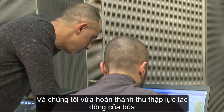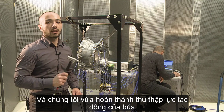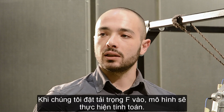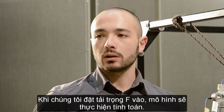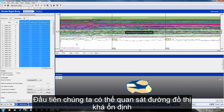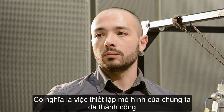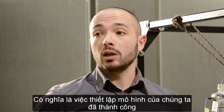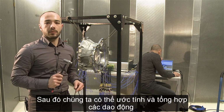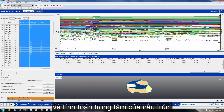So now we just finished acquiring all the FRF with the impact hammer. When we load those FRF in the rigid body mode calculator, first of all, we can observe that we get a pretty stable mass line, meaning that our identification will be probably quite successful. We can then estimate and synthesize the rigid body modes and calculate the center of gravity of the structure.